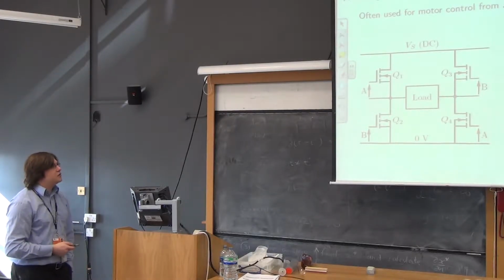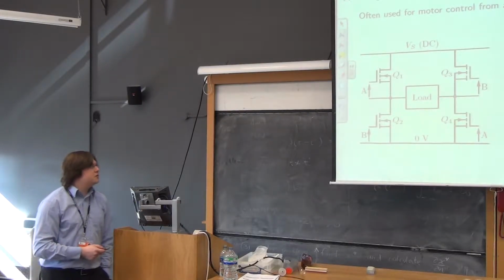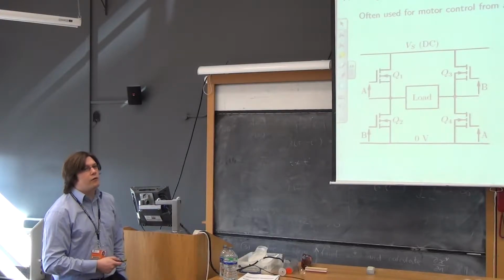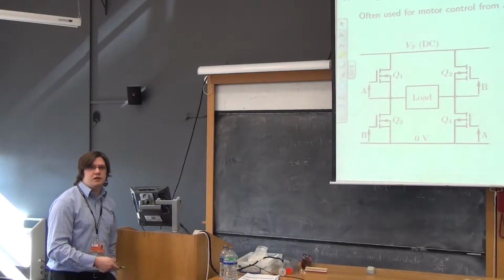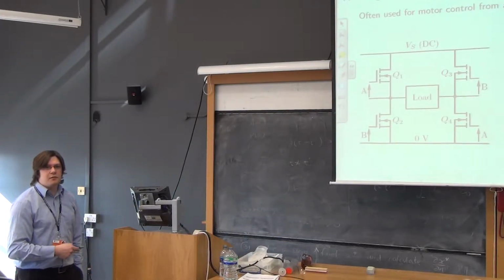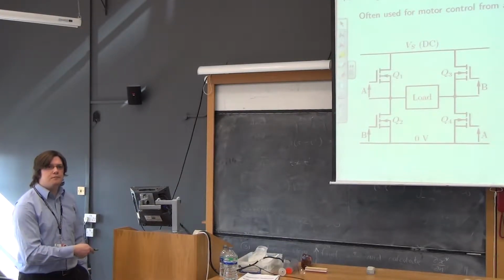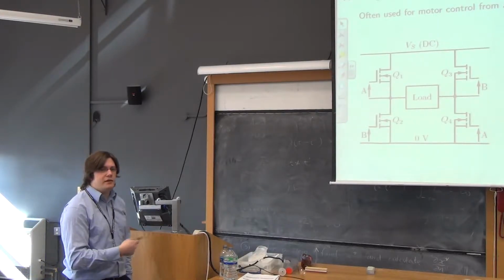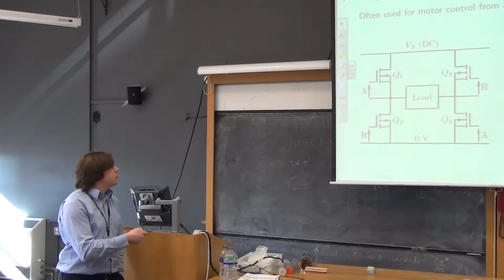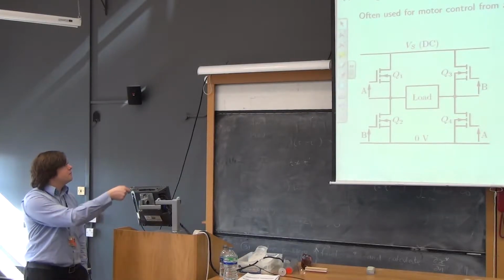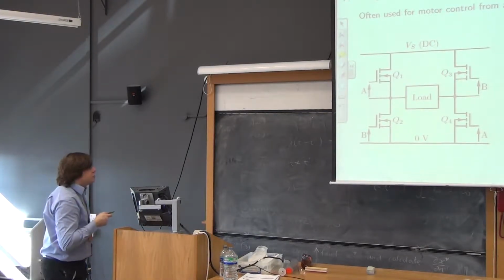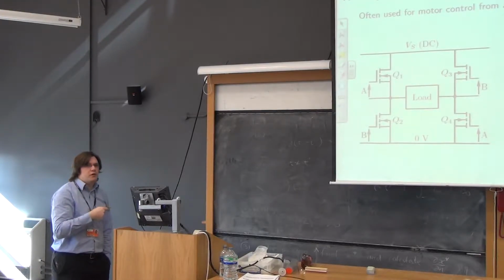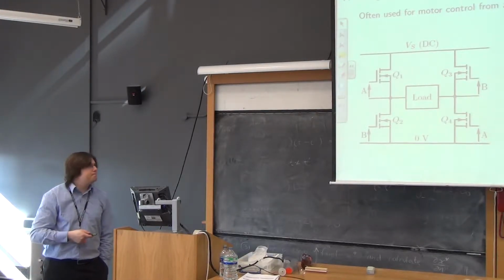And it just so happens that for the battery pack they've got, it's about 220 volts and about 110 amps when it's going flat out. And that's either 110 amps from wheels through generator into battery, or 110 amps out of battery through motor into wheels. Depends if you're slowing down, speeding up. And by controlling the switches, that's Q1, Q2, Q3 and Q4, you can adjust how the current flows, by what amount and in what direction.